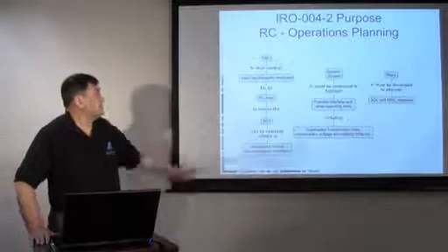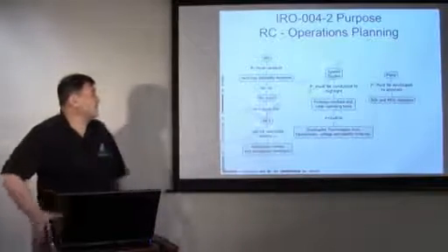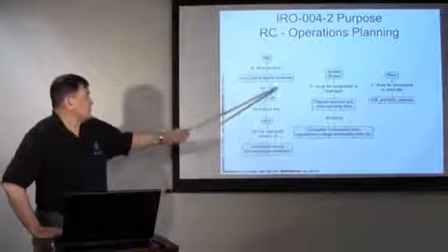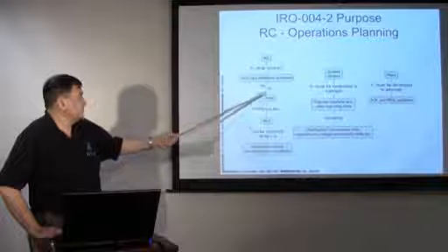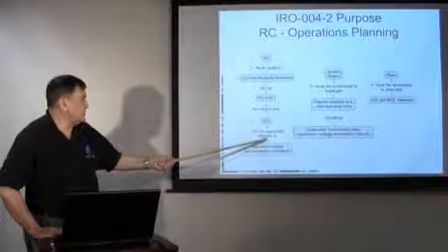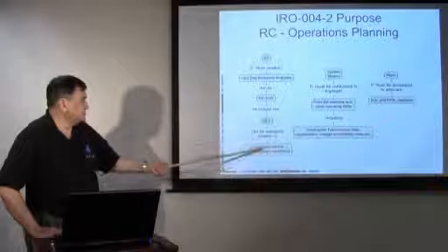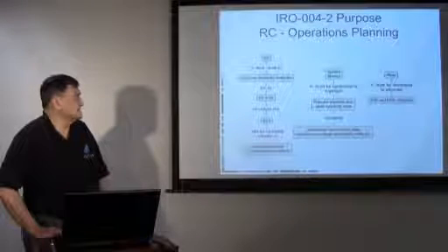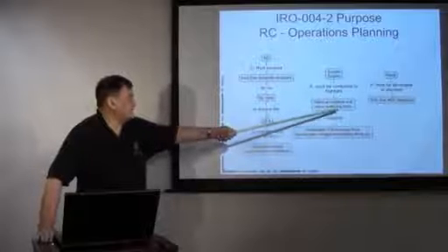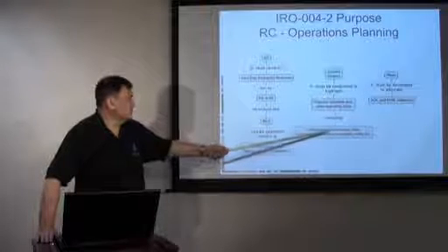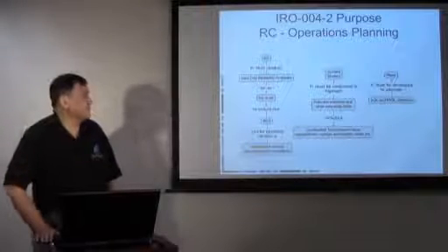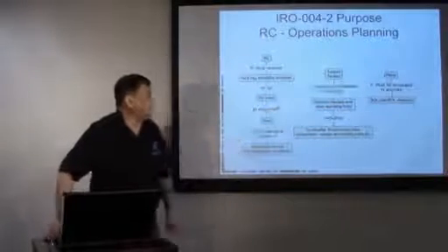This standard, 004, is highlighting the operations planning that the reliability coordinator will conduct for its area: a next-day reliability analysis to ensure that it can be reliably operated in both anticipated normal and emergency conditions. Those studies will highlight interface and other operating limits, including overloaded lines and transformer voltage stability limits. And they will build plans to alleviate those violations.